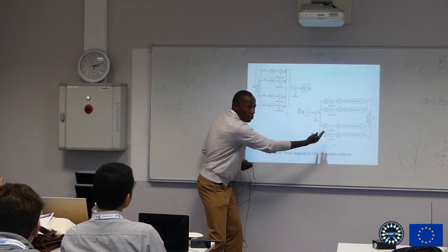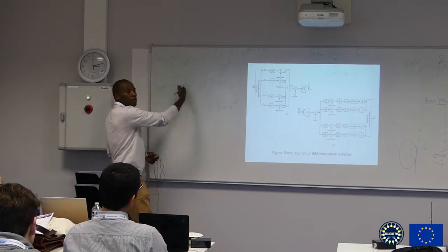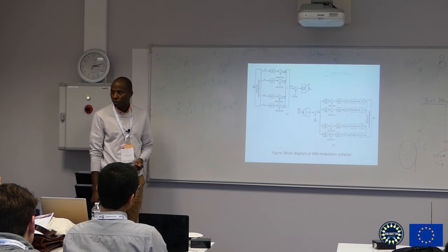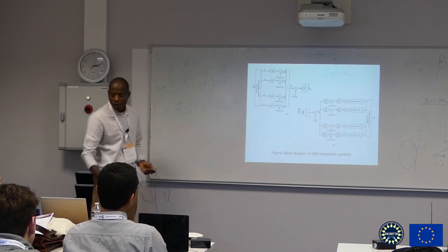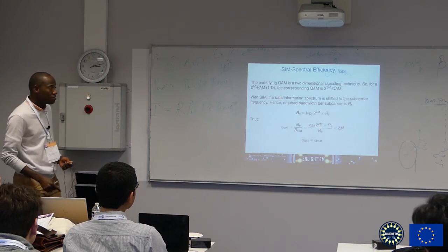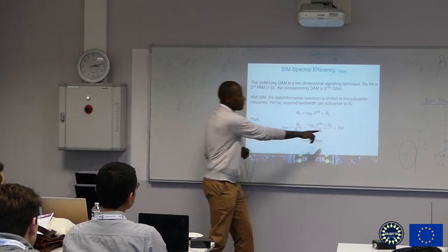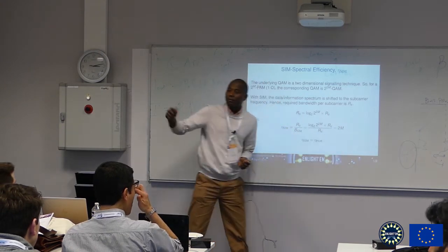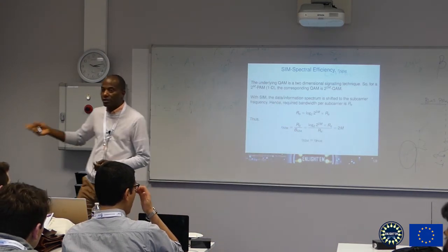And then if we have multiple, again, we do multiple, and we get our information. That is how we can use things like QAM in optical, based on subcarrier intensity modulation. We can have multi-carrier, we can have single carrier, that's fine. Again, we look at the spectral efficiency, you walk it through, efficiency is going to be 2M. The steps are there, where M is the number of bits per symbol.